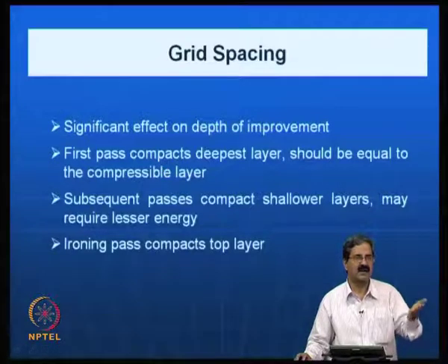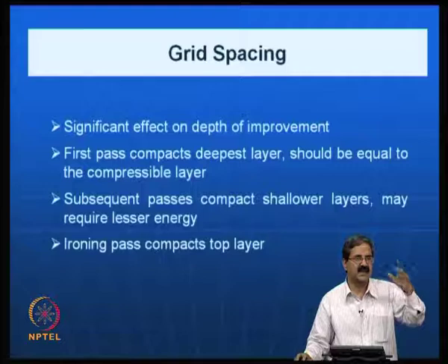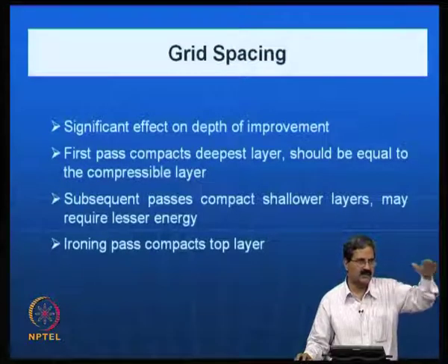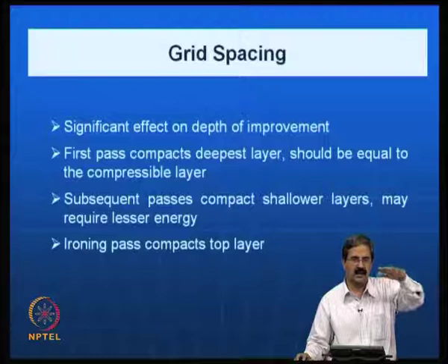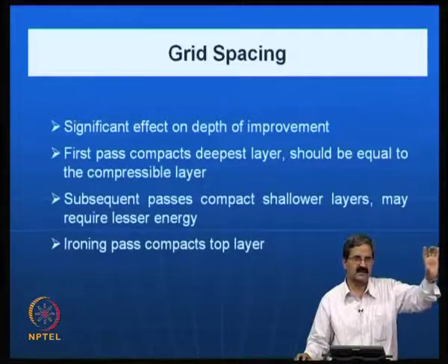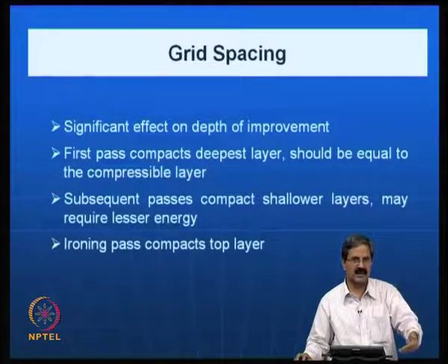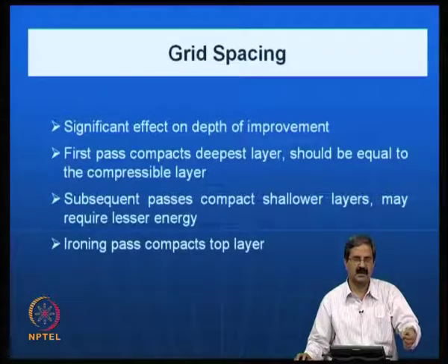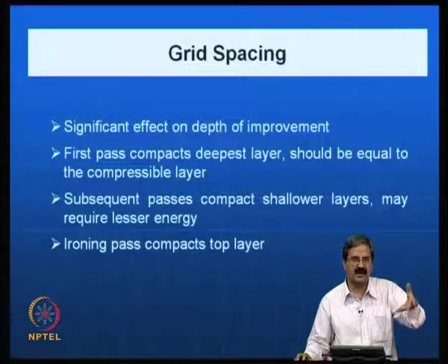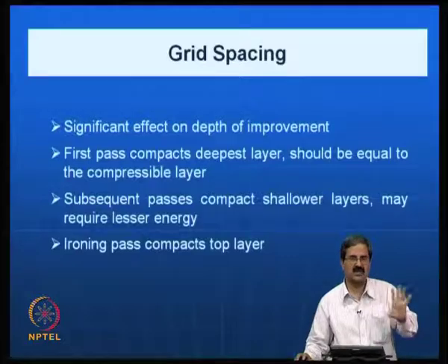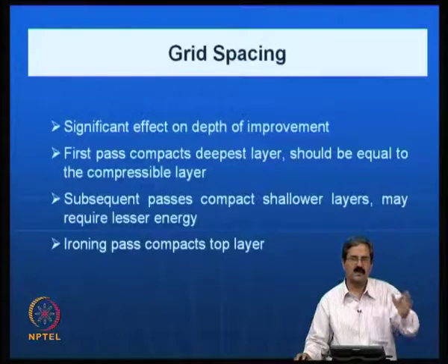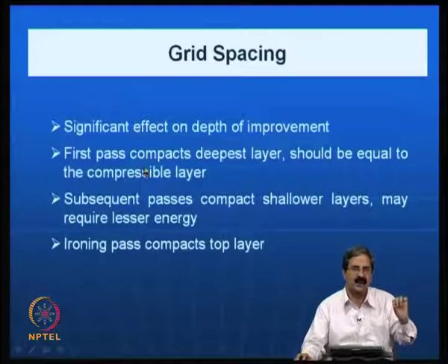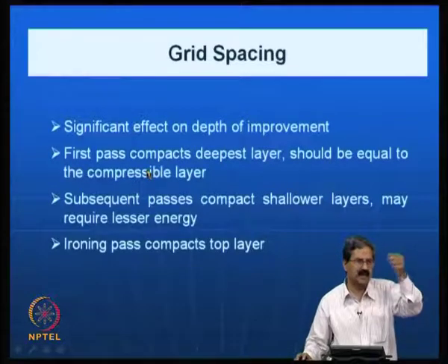You should be able to do some sort of analysis where, okay, you have a soft soil area and you construct all the buildings there. Then what is the load being transferred, and to what point? Suppose I assume that the soil is soft, up to which point are the stresses going? Suppose I compact very well and make it very strong, the stresses will not go deep. So you must be able to compare how stress actually gets mobilized when you apply load.